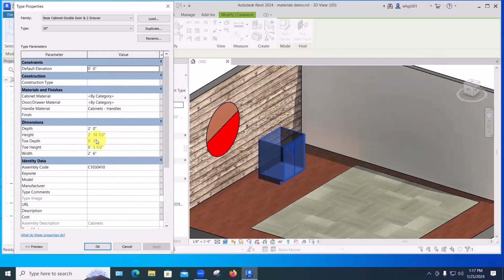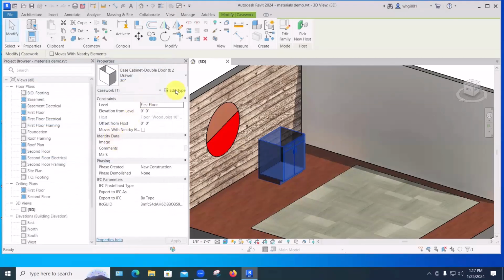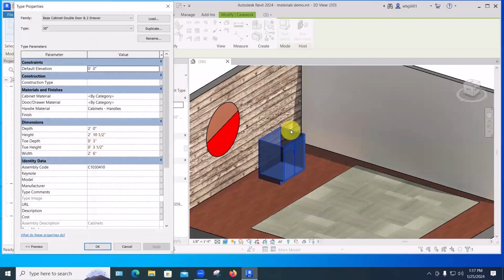I've seen the word used a couple of different ways, but in Revit, a parameter is information you enter at the project level, either here in Properties or in Edit Type, to modify something over here, either the size or materials, without having to go and edit the family. Here's how this works. Let me go through this first one, then we'll do 3 exercises together, and then you can go off on your own with your own objects.